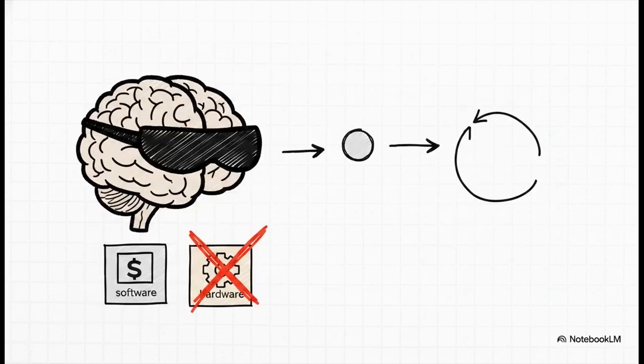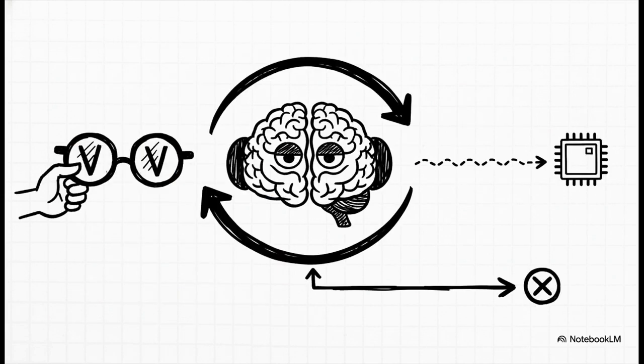But here comes our smart compiler again. It analyzes the code and says, nothing inside this software loop ever changes the reg variable. So obviously, it's always going to be 0. I can optimize this by just turning it into an infinite loop. The compiler is totally blind to the fact that the hardware itself, something outside the software, is supposed to change that value. And the solution, once again, is our friend volatile.